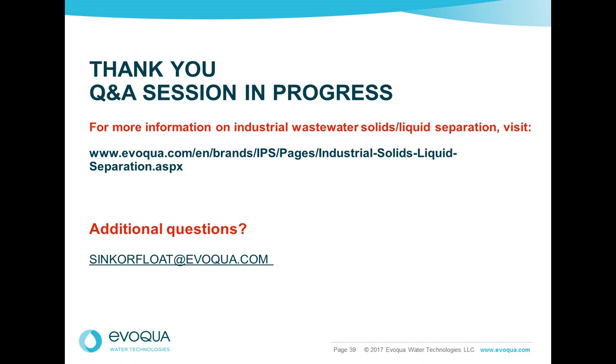I'm not 100% sure if that's referring to reuse or recycle back into the system if for whatever reason the effluent doesn't meet requirement for the downstream effluent quality. But nonetheless, that's a real common thing. More and more we're seeing reuse requirements, and as long as the clarifier is producing effluent quality, namely TSS or suspended solids, that meets whatever that downstream use is, it's very common.